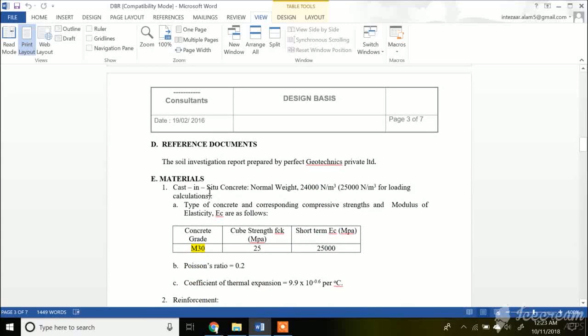The code does not include your soil report, your foundation design. For that you have to attach the soil investigation report, which will be prepared by the geotechnical agency, that is the soil investigation agency. So we will get the soil report from those soil investigation reports. If your consultancy is doing the soil investigation, then you can attach the soil investigation with your DBR, but keep it as a separate document. Please don't include the soil investigation report in the DBR. You can just mention the soil bearing capacity or the recommendations as per the geotechnical investigation.